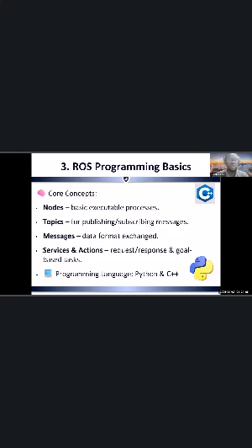It's actually more for obstacle detection. What LiDAR does, I'll show you what a LiDAR looks like. I think I have a picture of a LiDAR. It sends laser beams for depth perception. We also have different types of cameras, the RGB and the RGBD cameras. The RGB are the normal color cameras. I've worked with an RGBD camera, which has a laser beam in it that measures depth. LiDARs are basically for dynamic obstacle detection. It rotates 360 degrees and sends laser beams.